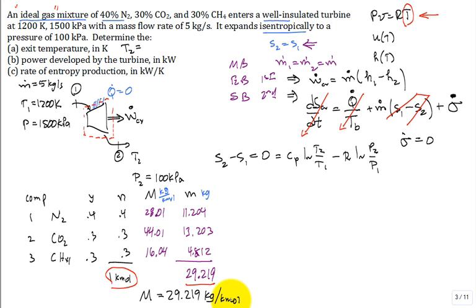I'm going to use that polynomial expression for the temperature-dependent specific heats of methane. It's in the table. I'm going to use that in a minute or two. But basically, I'm going to use that not to integrate the polynomial, but to simply evaluate that polynomial at one temperature, which is the average temperature, so that I can just use a constant specific heat evaluated at appropriate average temperature. But methane is the real challenge here.